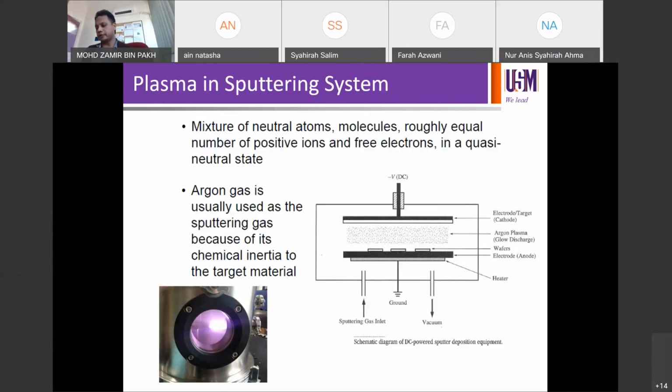In this particular case, you don't want that to happen. So that's why the gas used for plasma formation needs to be inert, right? For example, argon. On the other hand, there are cases where you want to use the gas to produce compound on the deposited layer.